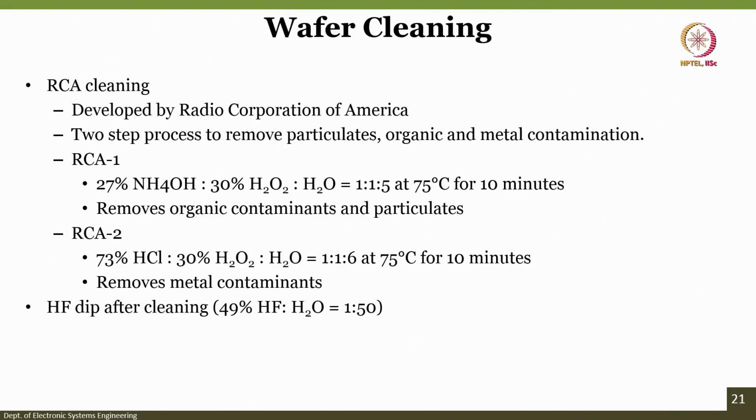Now, once you have a wafer, even a new wafer, there is a formation of a thin silicon dioxide. Why? Because silicon when it reacts with oxygen forms SiO2. So, the oxygen present in the air will also cause a thin layer of silicon dioxide. To avoid any oxide when you start the wafer processing, it is important that you clean the wafer.